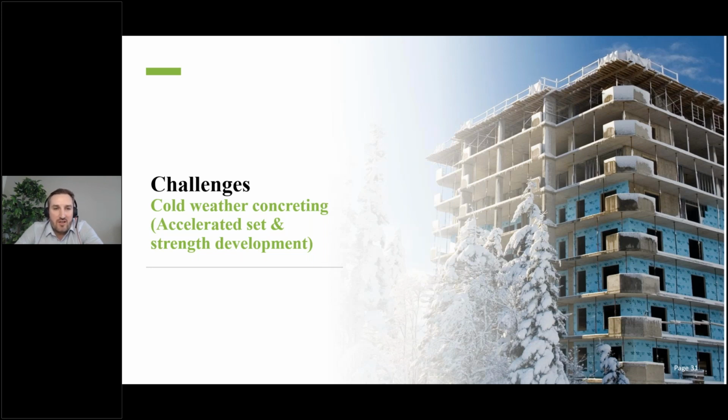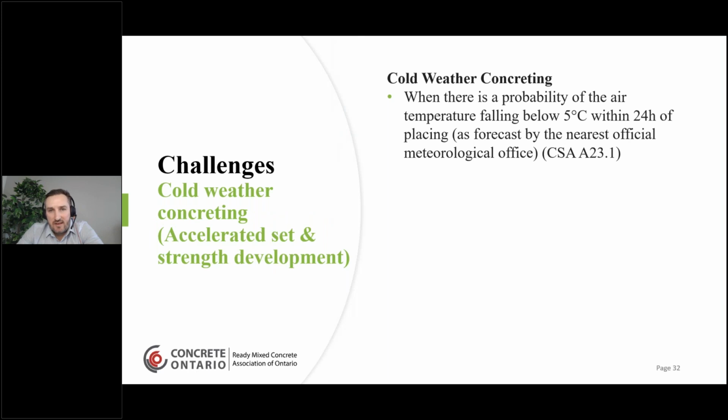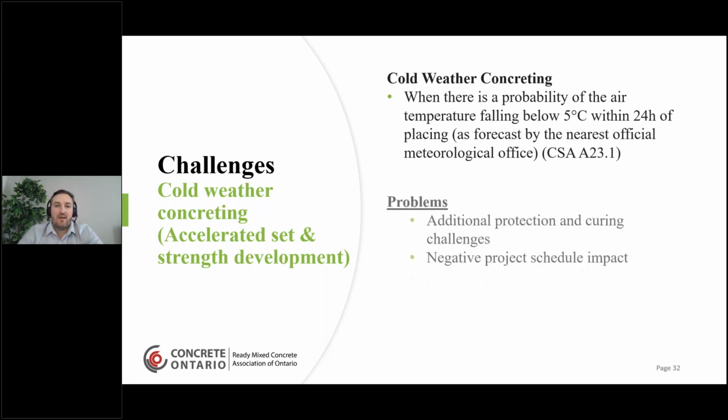So one big challenge, obviously, cold weather concreting. In Canada, we have a lot of minus 20 days, minus 25 days. We do require accelerated sets and strength development, and it will impact your carbon budget. So cold weather in Ontario is defined as when there's a probability of the air temperature falling below 5 degrees C within 24 hours of placing. So that's taken directly from CSA A23.1.